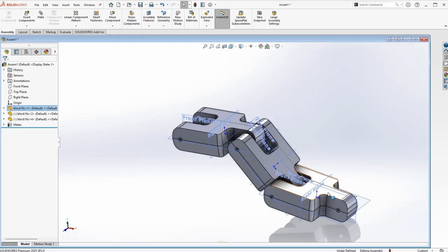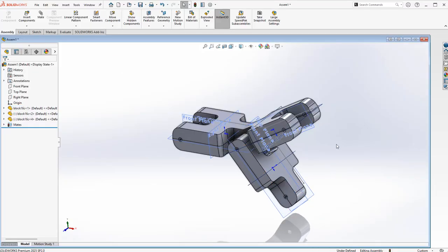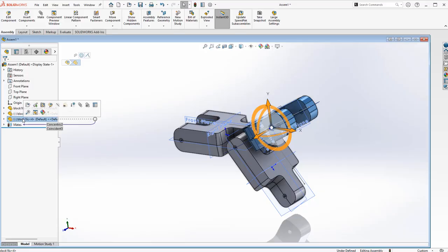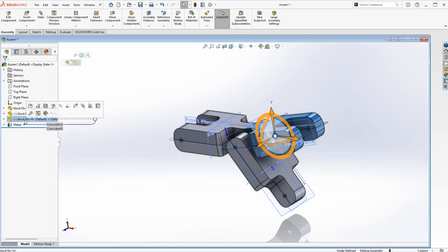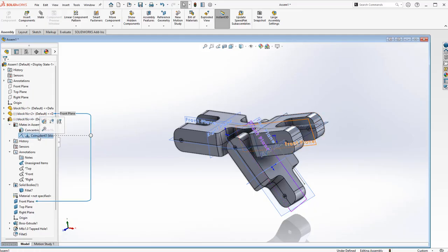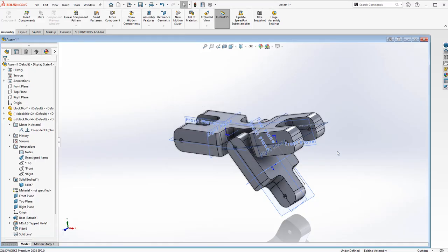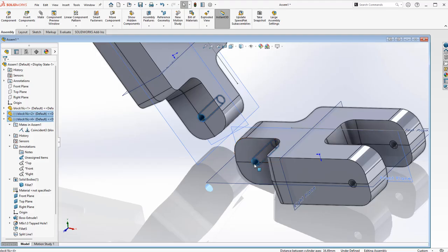Let's test it to see if we can flex our model. Okay, nope, it re-referenced everything to the same one. All right, so I'm just going to try to pull this one. Let's see, in the third one, I'll open him up. Oh, yep, find my references. I'll just flat out delete the concentricity reference. Now I can pull on him into a different location and reestablish that reference.